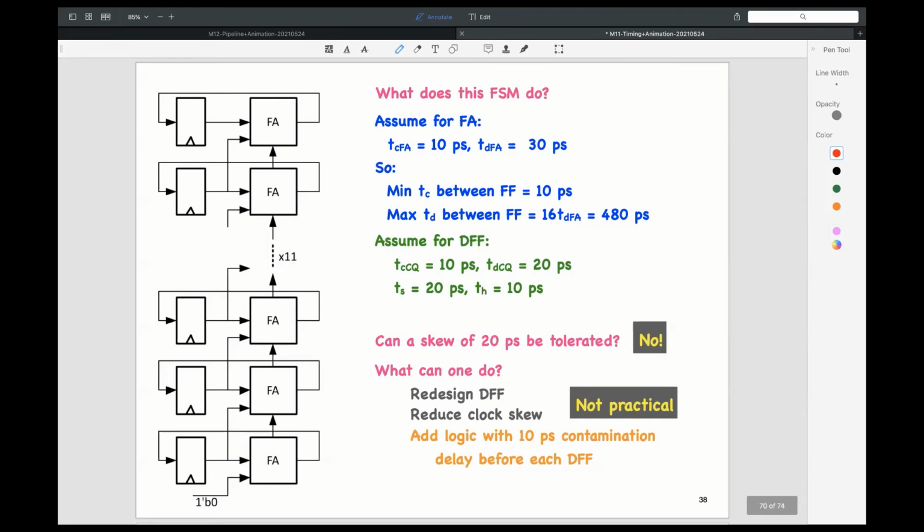Fundamentally, therefore, it is impossible to prevent setup and hold time violations from happening, unless your system is sitting in an isolated universe where everything is under your control, which no practical system will be like, right? It's inevitable that your design will get signals from outside, and therefore inevitable that you have a chance that they will run into violation of setup and hold time.